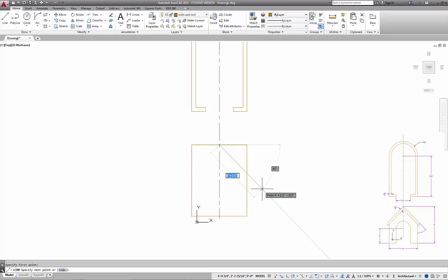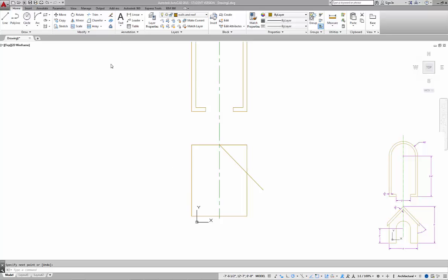Well, what's 45 degrees? Remember, we lock it in at 15-degree increments. So I can come down and you can see that I am right at 45 degrees here. There I am, 45 degrees. And it's 315 degrees, which is 360 minus 45. So that's my 45 degree line. I'll just draw an extra long line here. We'll draw the same line on the other side.